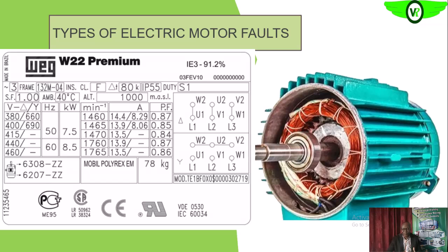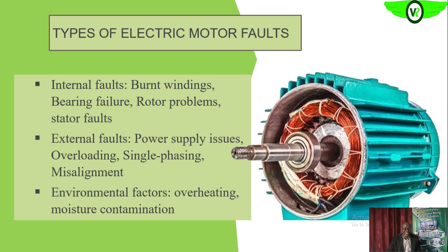Ambient temperature will add up to the internal heat generated by the winding itself, and that can result in overheating if the insulation of the motor is not designed to withstand that level of heat. Of course, that can result in failure.